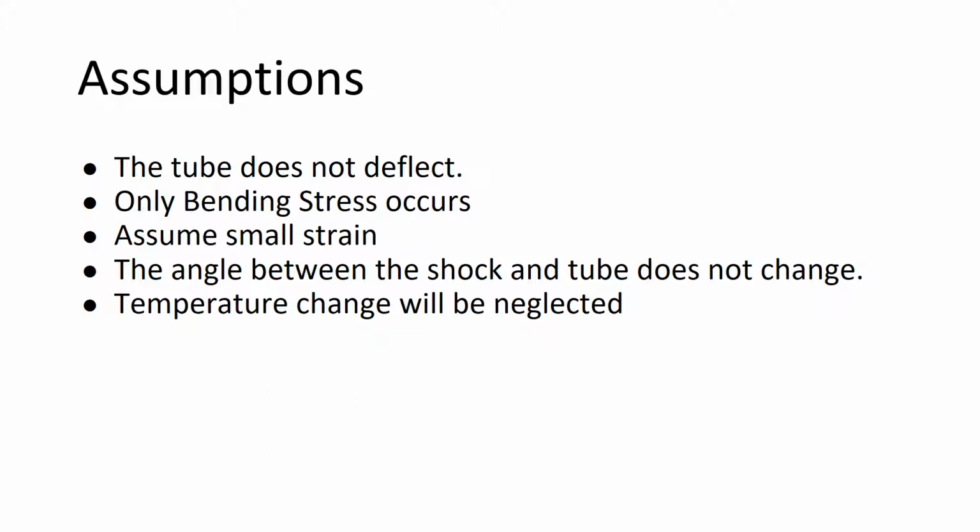Assumptions. The tube will not deflect. Only bending stress occurs. A small strain is to be assumed. The angle between the shock and the tube will not change. Temperature change will be neglected.